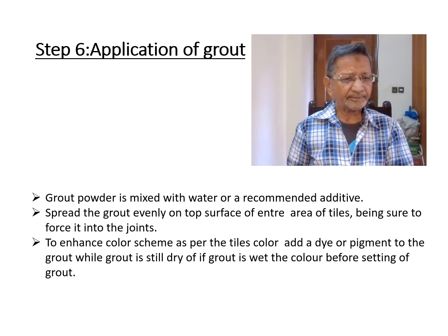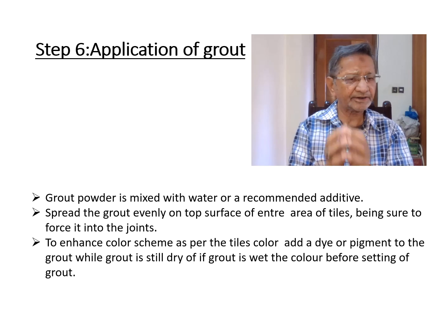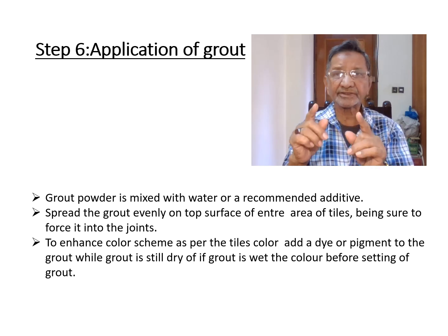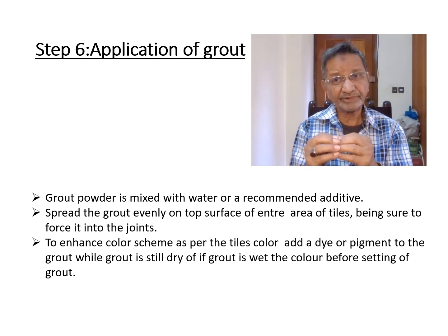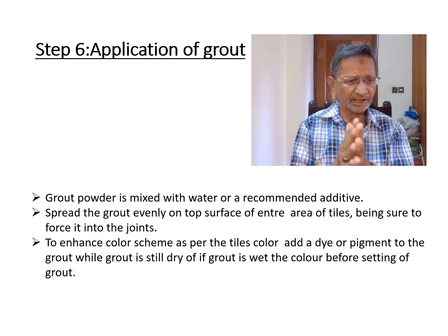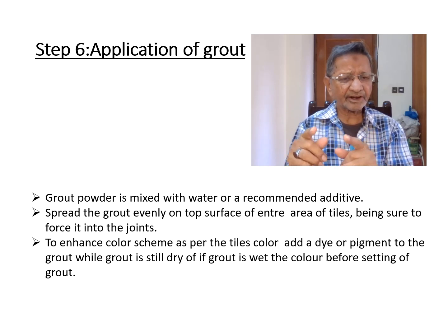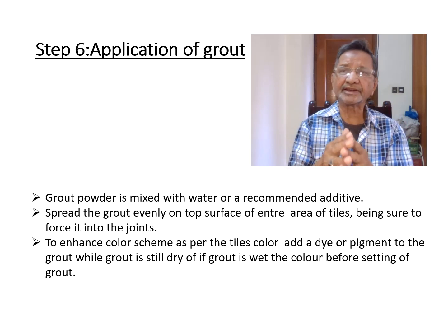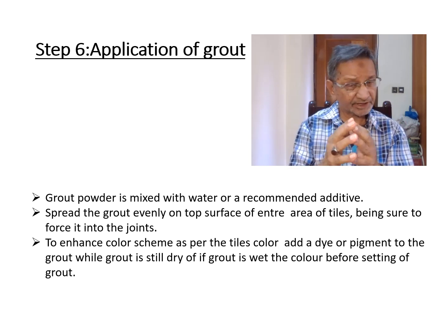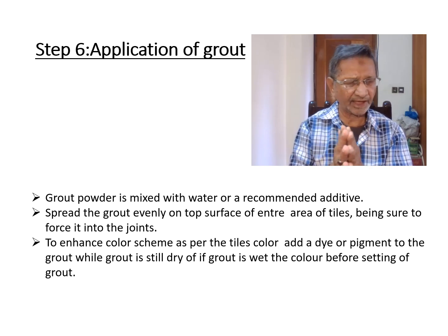The grout powder should be mixed with water or the recommended additive according to the manufacturer's instructions. The grout should be done very carefully. Apply the grout evenly across the entire surface of the tile, ensuring that it is pressed firmly into the joints. You have to check these things again and again and keep an eye on that.